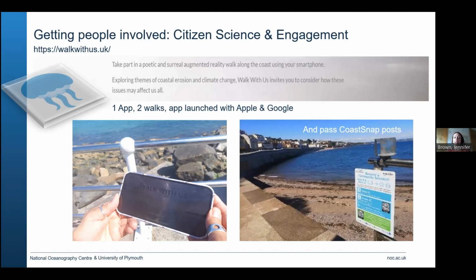And over many years, this will start to build up to show trends, not just the seasonal cycle, but the long-term trends in the beach levels at this site. And this is important because scour at the seawall can pose a failure hazard, which we don't want. And also, lowering beaches enable larger waves to impact a seawall, so you get more overtopping hazards. So there's more risk to the trains and also the pedestrians on the platforms waiting for the trains.